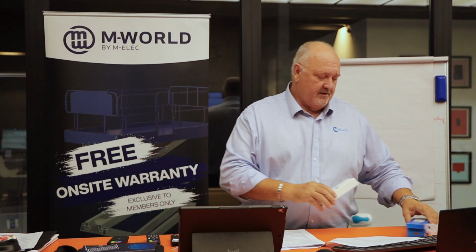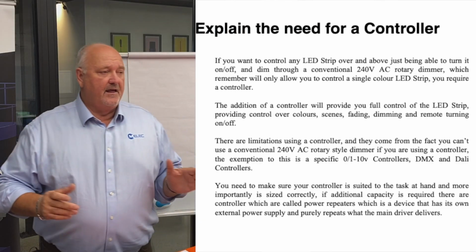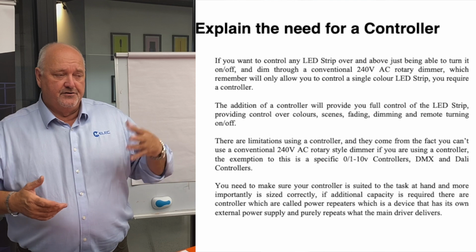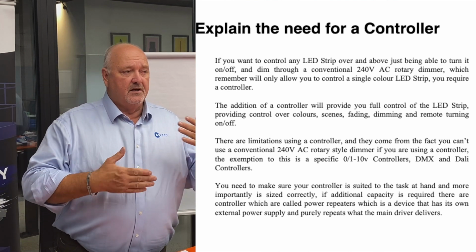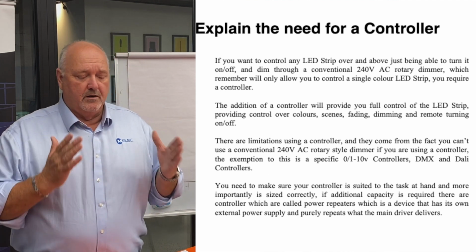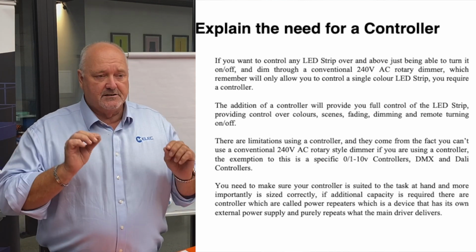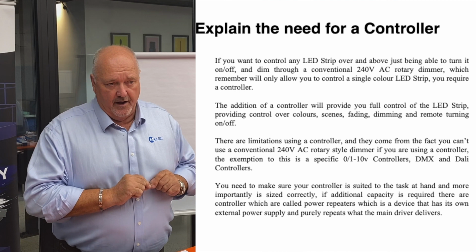These will not work with this. This is a DALI designed LED strip driver. All right, so as simple as that's put. And then we have our ML2002, which will do the 0 to 10, and we have a DMX driver. So drivers are available, but what I'm saying here is they are specific to the purpose that's required.